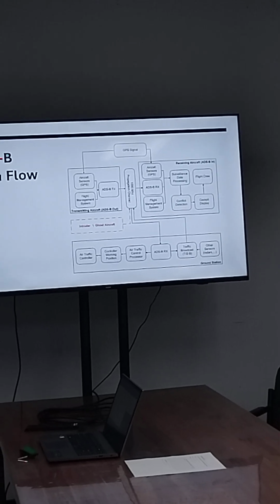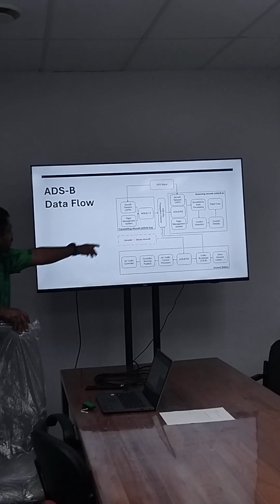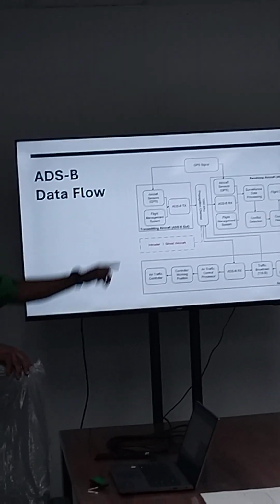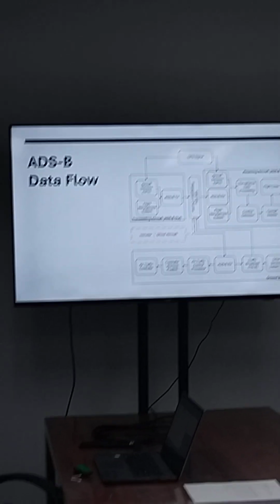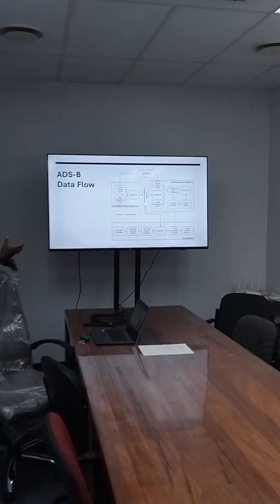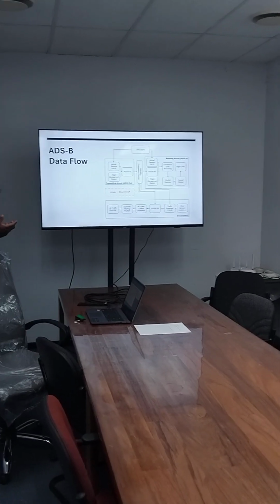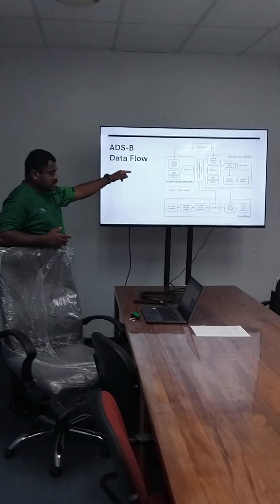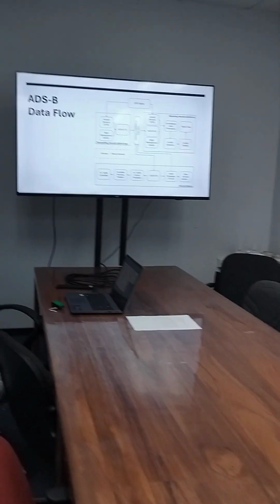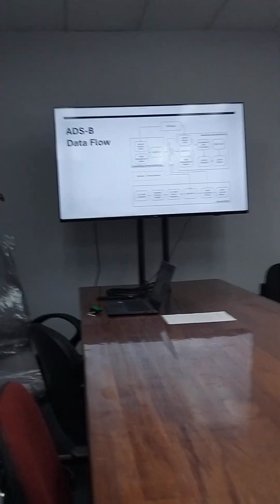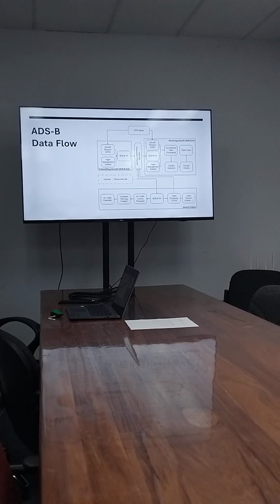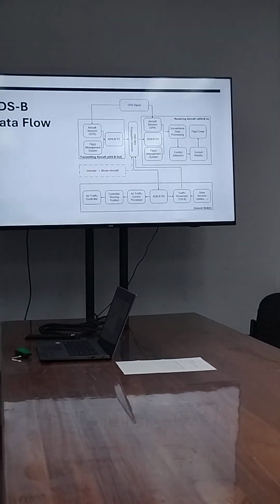So you can see the ADSB transmitter from the cockpit transmits on 1090 megahertz. ADSB frequency is 1090 megahertz. That means we receive on 1090 megahertz, and they transmit on 1090 megahertz. There's no other frequency. It's only ADSB out, meaning transmitted from the aircraft at a frequency of 1090 megahertz. So our ground station receivers will be tuned to that frequency.